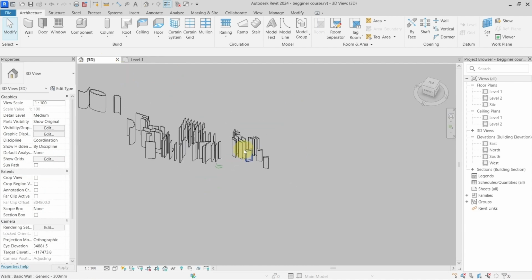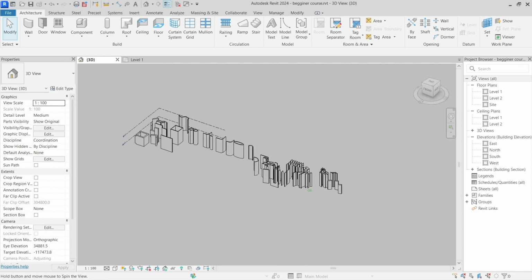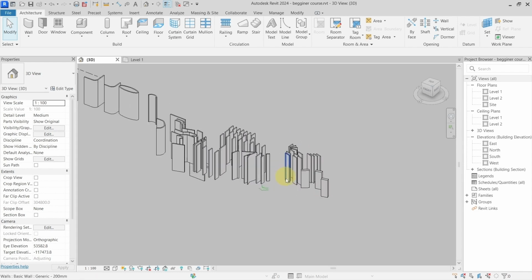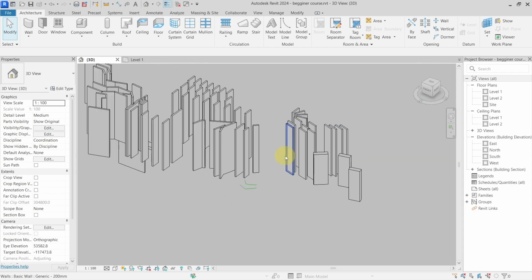But if you go to 3D, you can see that Revit needs to know which plane to use to create the dimension and measure in there, because it can only measure in a plane. For this, there is a setting here under the Architecture tab, this one, Work Plane, where you can either show and set the work planes and so on and so forth. So let's now go with showing the work plane.